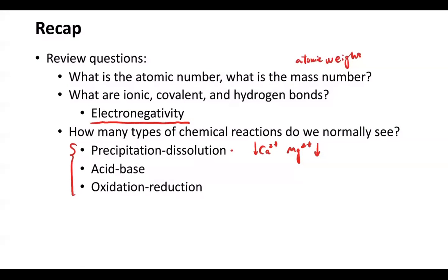So there are also reactions that are categorized as oxidation reduction reactions. We mentioned that a major application is to remove the organics in the water because quite a lot of organics are being dumped into the wastewater. For example, the leaves or the biomass, right? And from household industry, there are also a lot of organics being discharged into the water. So we have to oxidize them before we send them into the water bodies, right? Also because these organics are generally quite toxic to humans, right?